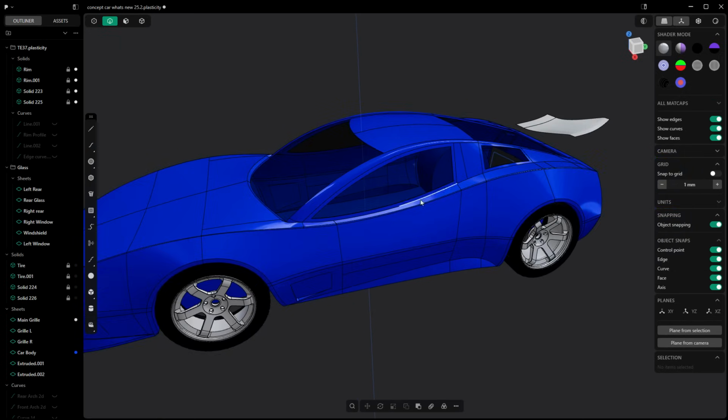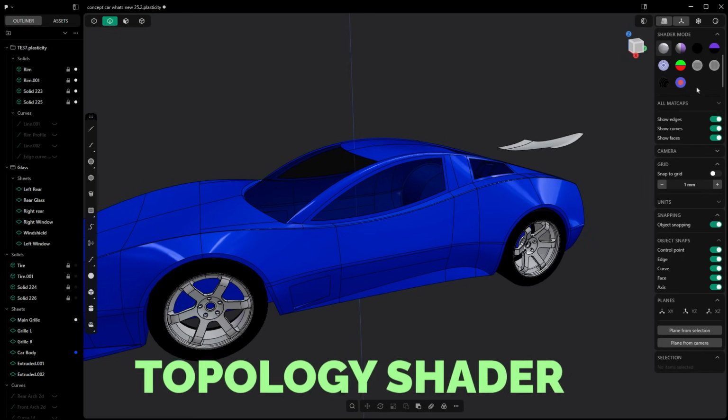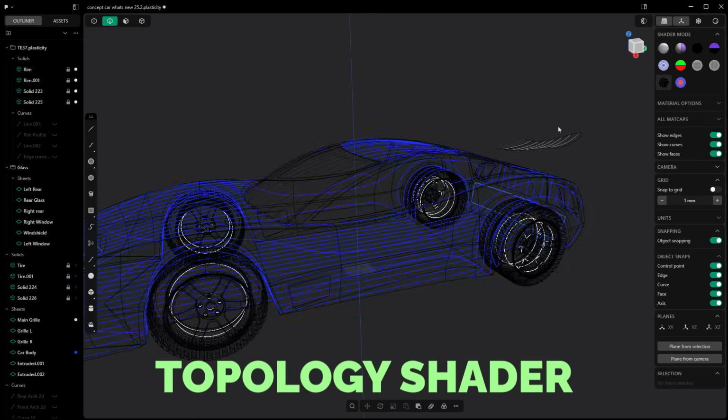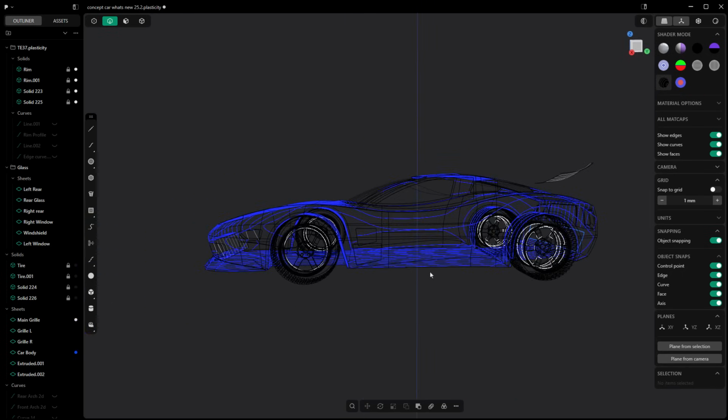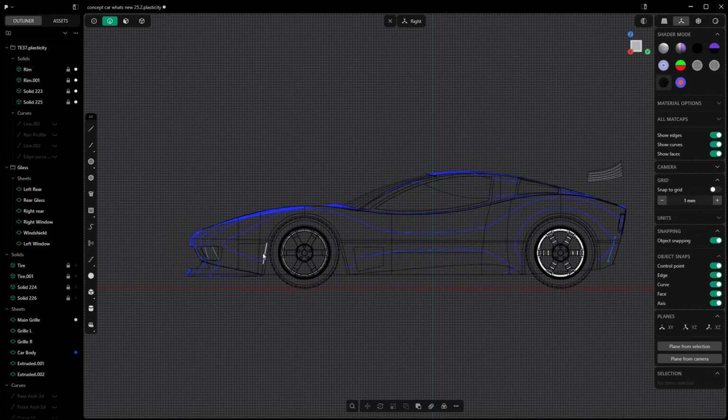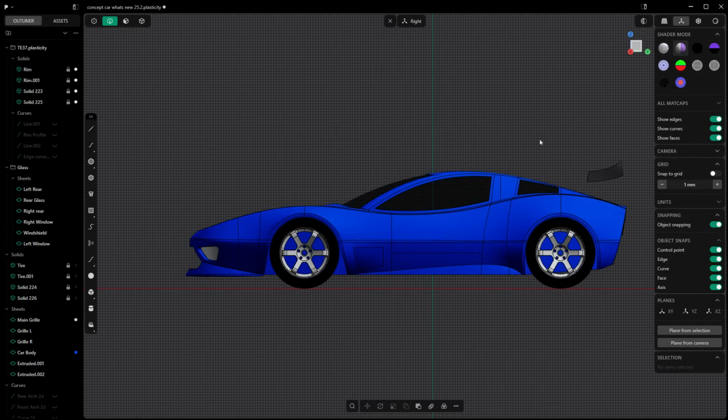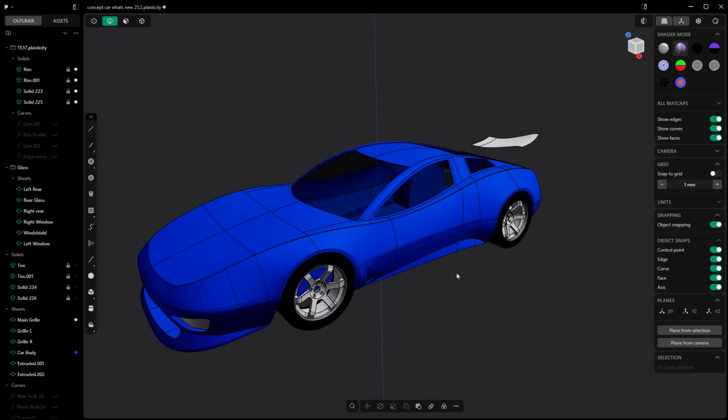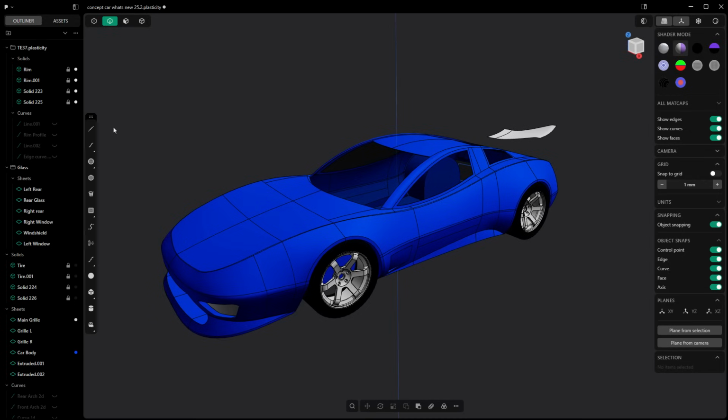While we are talking about measuring continuity and looking at our designs, there is also a new shader mode option that allows us to put this sort of overlay of curves on our design. This is a pretty neat way that we can identify and look at the curvature of a design, so we can see whether or not we need to make some changes based on what we think the curvature should do on a design like this. So pretty neat, a cool way to get an idea of how your designs are progressing, especially if you're doing complex surfacing work.